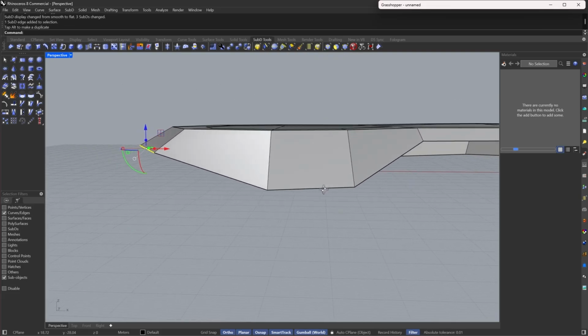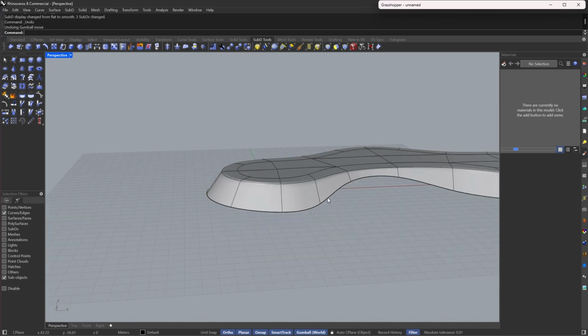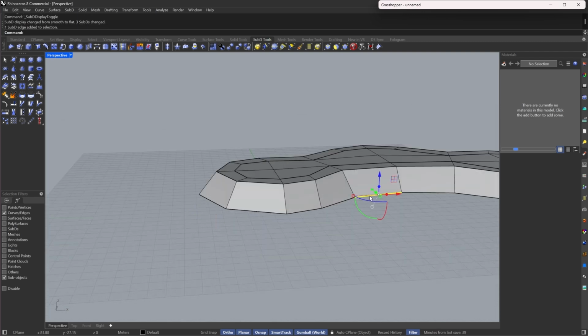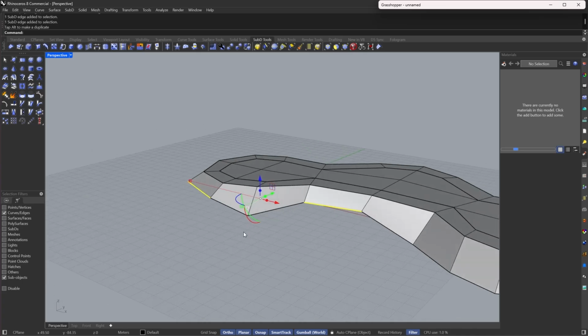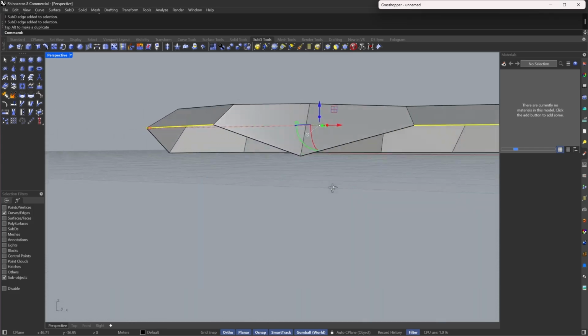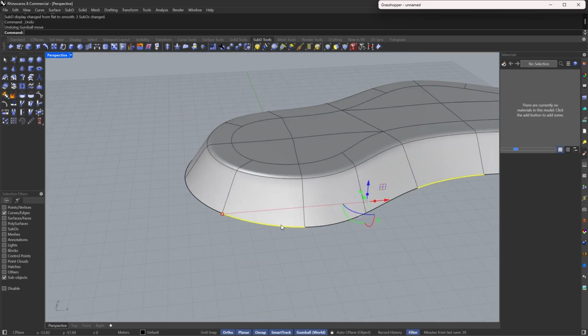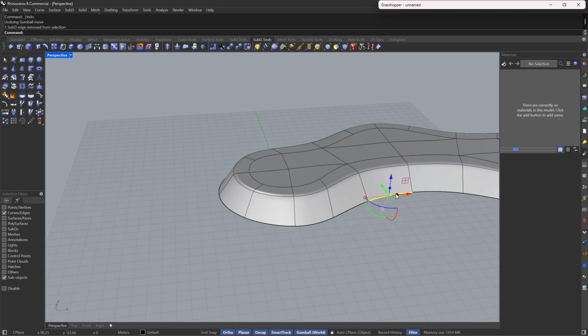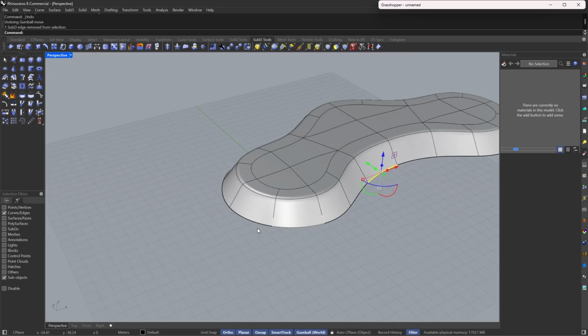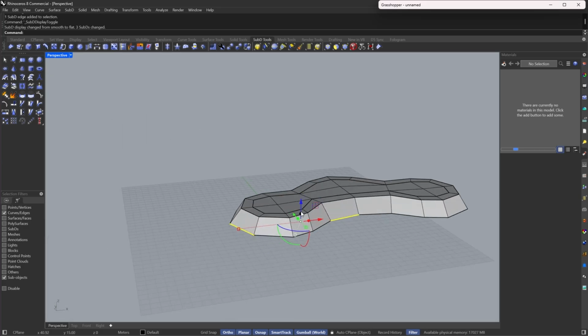But you have to be careful, because if you select, let's go back a little bit, if you select this and then selected, probably ignored 2 and then selected 1, then you will have this kind of point, and this point is not going to be structurally good, because in SubD mode it will go up. So you need at least 3. So if I selected this, for example, I have to skip 3 and then go to the 4th.